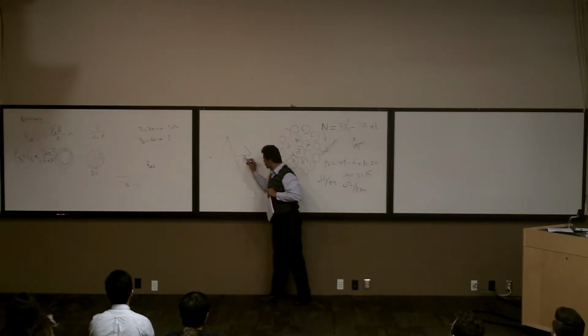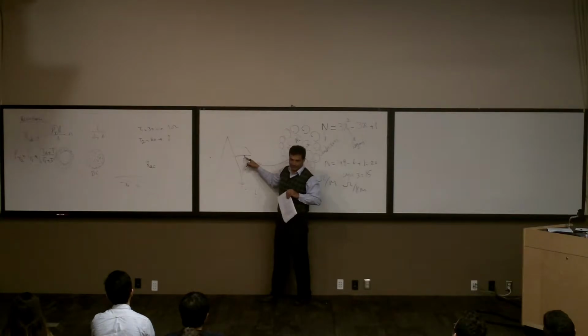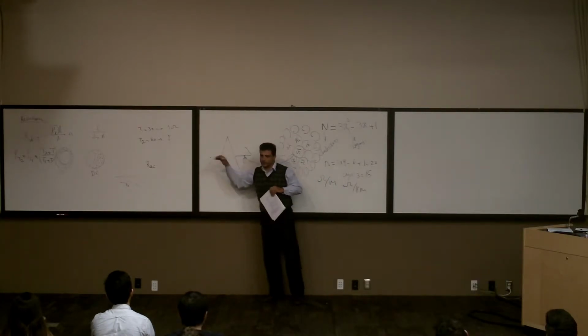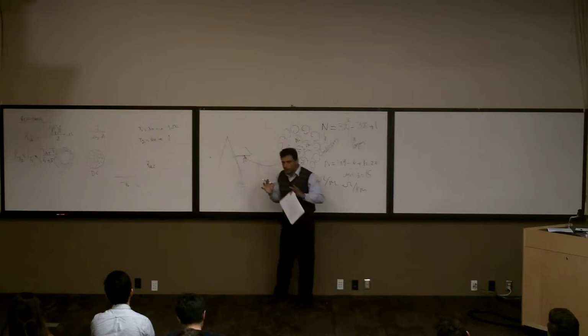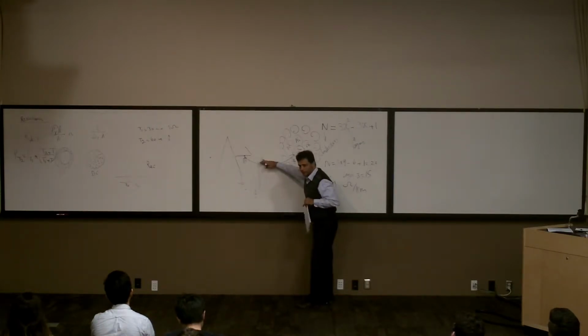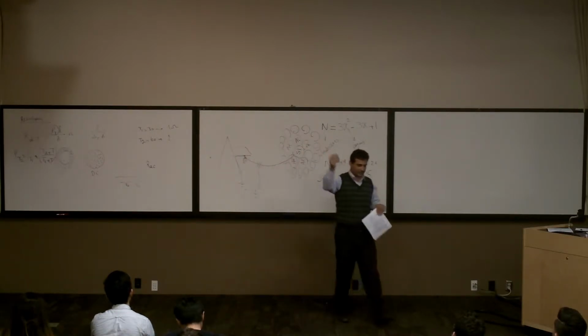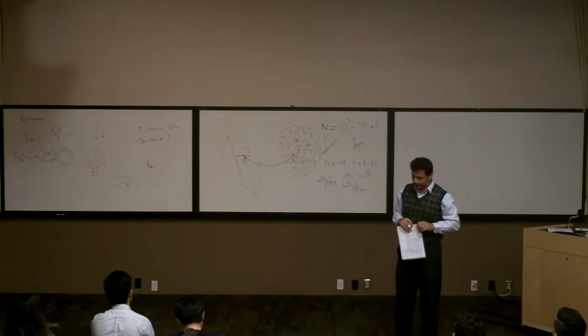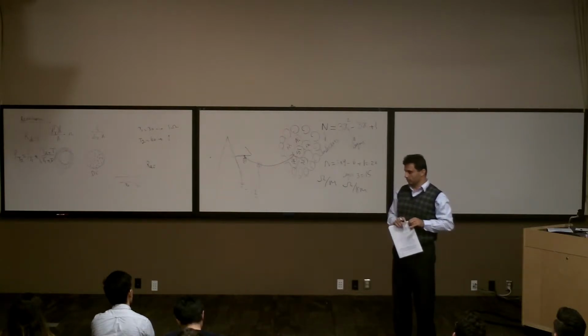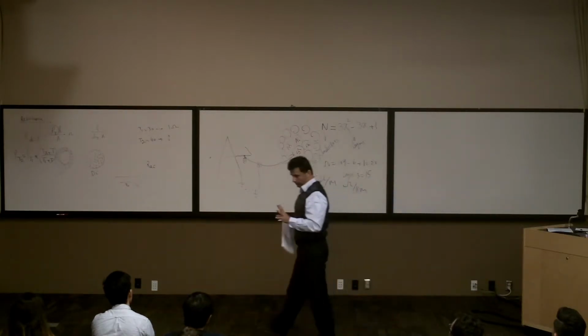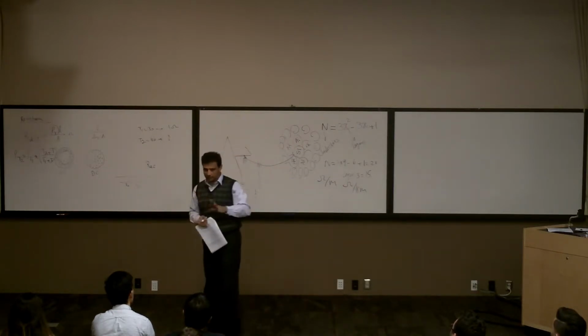But the current is going to go through the surface of this from here, and these towers are all grounded. The current is going to go through here. They call it again leakage current. It goes through the surface of this insulator. So my point is, there is some current going from the system, the voltage of the system, the hot wire, to the ground. They model this path, the value of the resistance of this path. They call it conductance. But all the time we ignore this, because first of all, it's a very small value. The leakage current is very small.